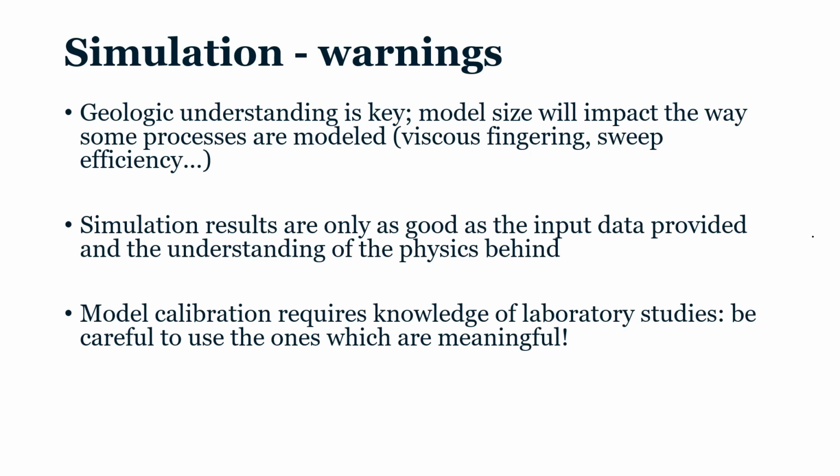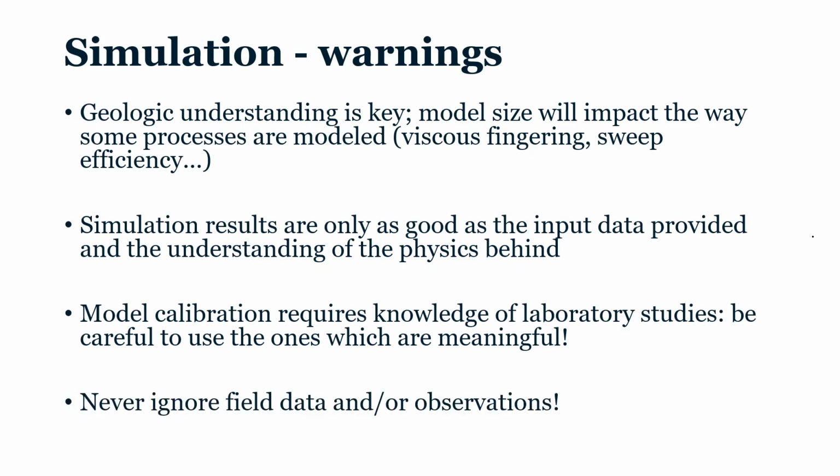So the most important data we will see are resistance factor versus velocity and retention. The rest, honestly, can be discussed. And never ignore field data observation. Spend some time reading the results of other people, not the simulation results, actual field data, especially injectivity or recovery and reservoir responses.